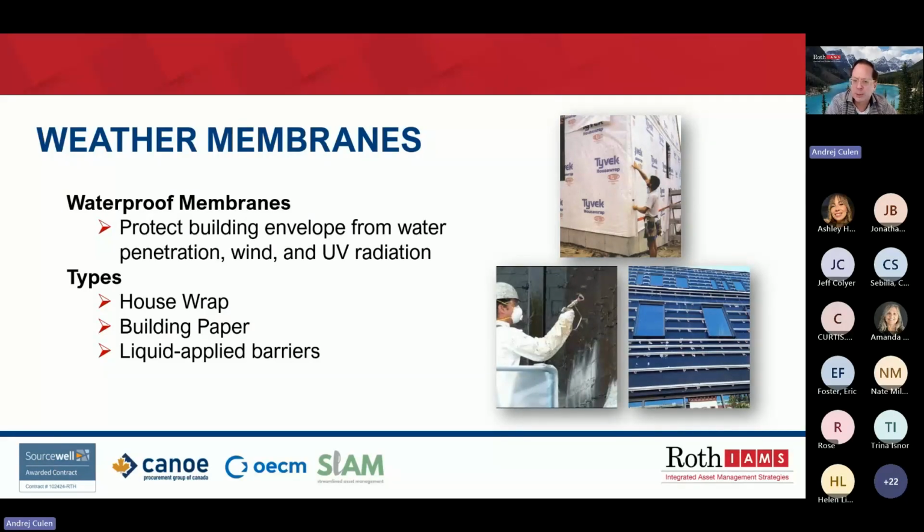Selecting the appropriate weather barrier material and ensuring its proper installation is crucial for long-lasting protection and durability. This may involve overlapping seams, sealing penetrations, and integrating the weather barrier with other building envelope components, such as flashings and window openings.